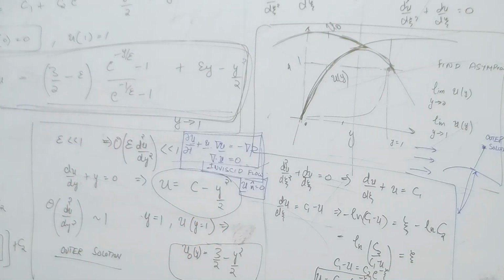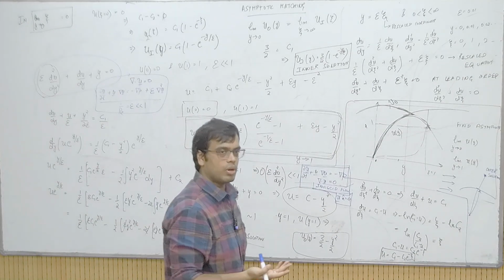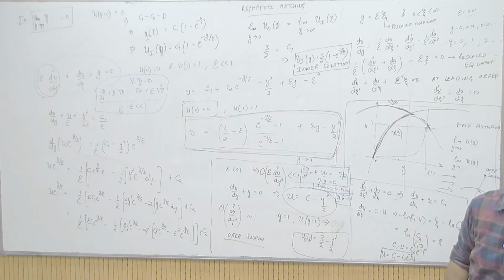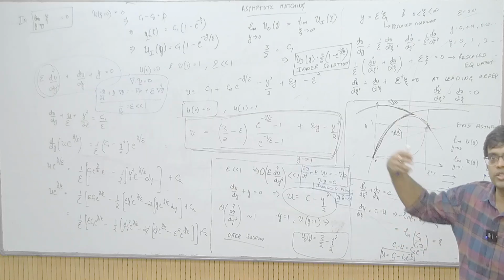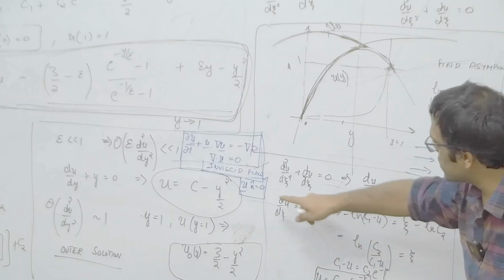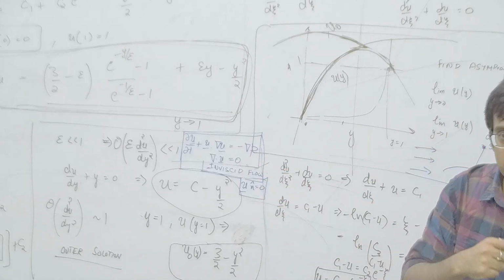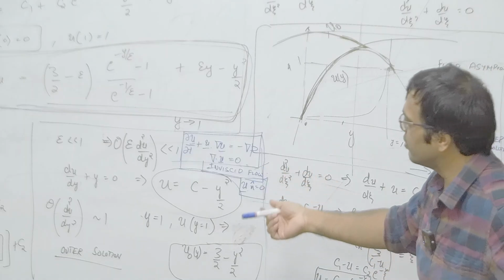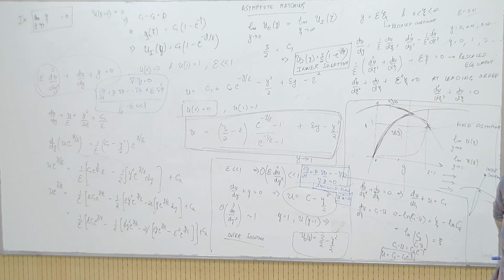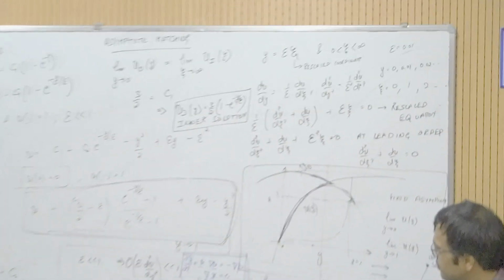But you cannot impose a tangential boundary condition on inviscid flows, because the virtue of the no slip boundary condition was viscosity and you have completely dropped the viscous terms. You cannot impose boundary conditions due to a physical phenomenon which you don't have in your governing equation. So the no slip boundary condition will not be applicable anymore. We have removed one set of boundary conditions, and now we have a closed system, first order equations, with a single set of boundary conditions in each direction.